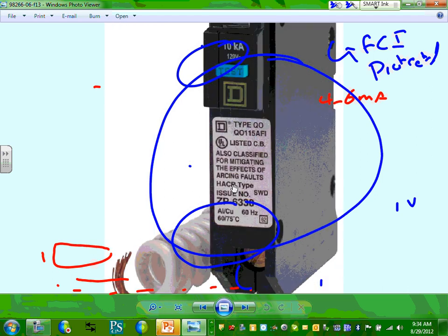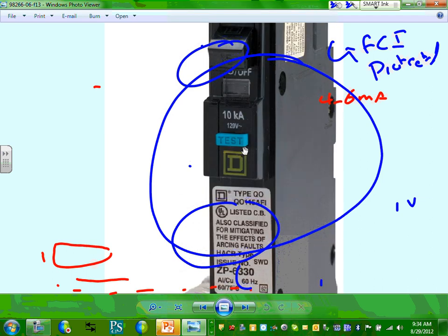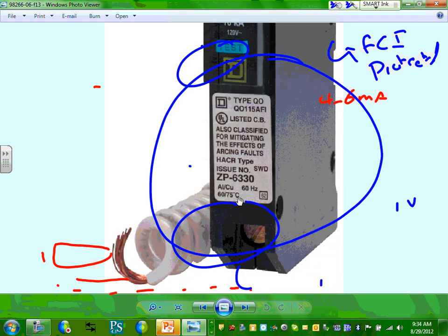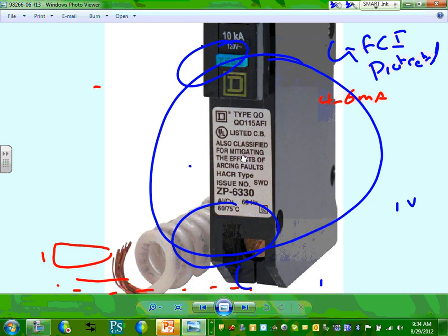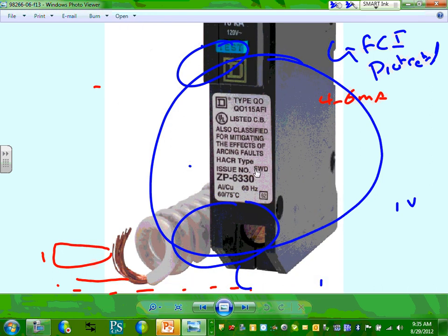This is a QP arc fault circuit interrupter, I believe, right? So does my QP arc fault circuit interrupter look like this, or is it a GFCI? Anybody? So this is my arc fault circuit interrupter. Yep, arc fault circuit interrupter. It looks exactly like the GFCI, guys. In, power, out. So you tie this to the neutral and you pull out of the circuit breaker neutral and hot.